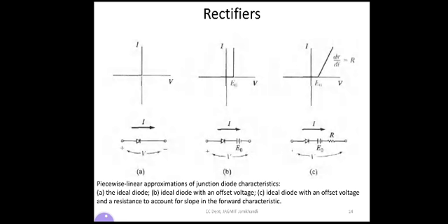So the rectified signal has a positive average value and therefore contains a DC component. So by appropriate filtering, you might have studied the rectifiers. After rectification, to remove the unwanted components, what are we using? Filtering. So appropriate filtering is used here to make it a complete DC signal. So by appropriate filtering, the DC level can be extracted from the rectified signal.